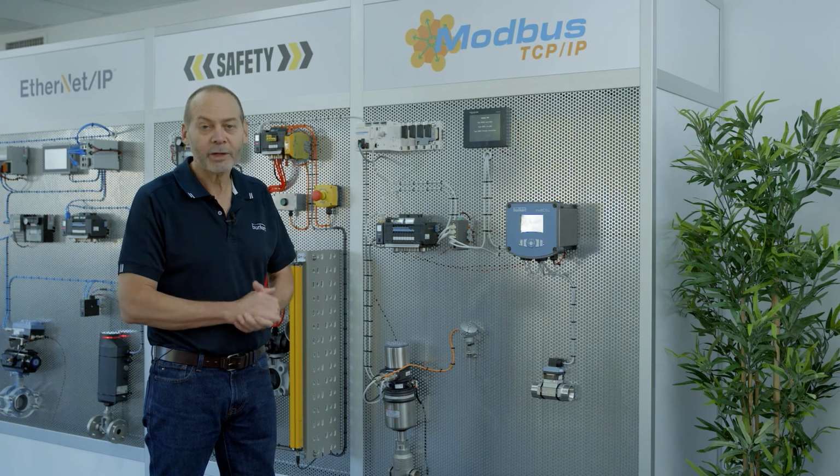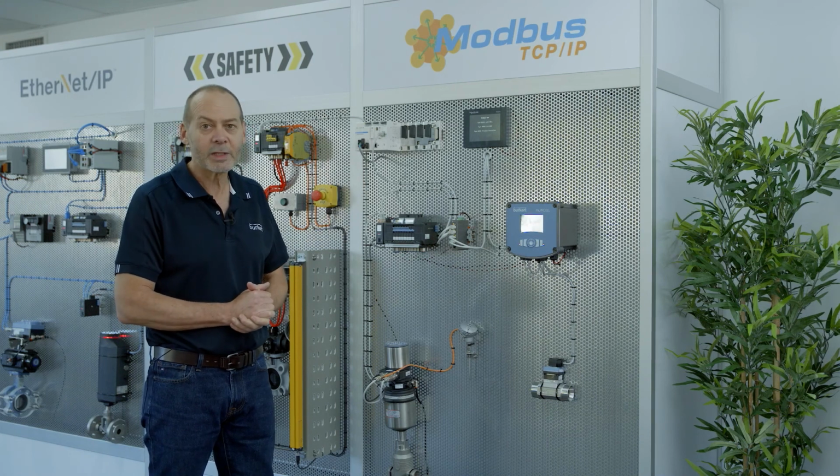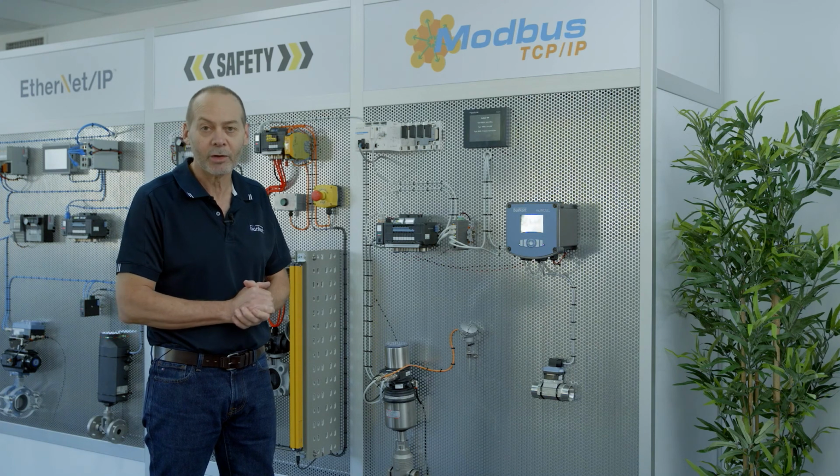Modbus was one of the original networks in its RS-232 and RS-485 forms, and it's now been integrated into TCP/IP. It was one of the first Ethernet networks available and is still widely used today as a very simple and low-cost network, and you'll notice that most vendors have Modbus TCP/IP available.